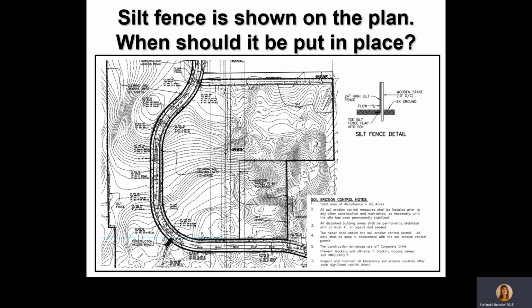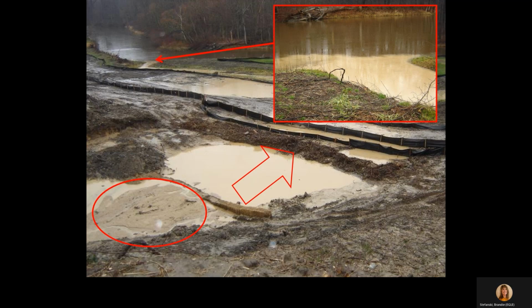of termination. This is from a large construction site in South Haven, Michigan during a light rain. You can see the sand particles settling out behind the straw barrier. The clay-sized particles are passing over the straw barrier, through a small sediment basin, through a brush barrier, through 3 layers of silt fence, and discharging into the Black River. This site is in Van Buren County and had sandy clay soils. Look at the sand that settled out first in front of the straw bales. However, you will notice the clay continued to discharge despite several SCSC measures in place.